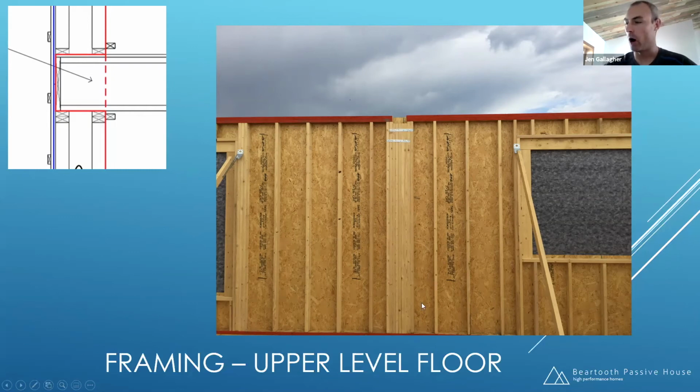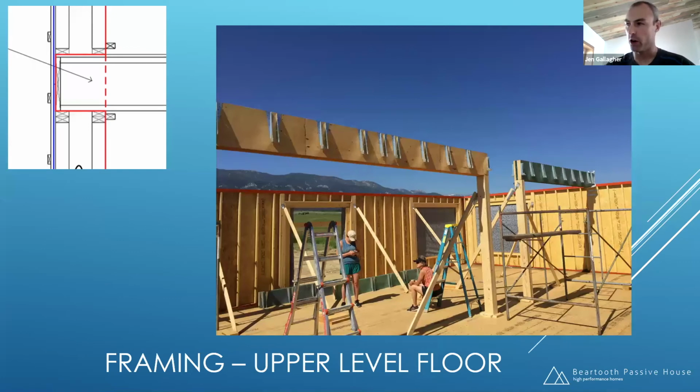Okay. Now I know that when I get to it, I've got to get my air barrier from inside, and I've got to get it out and around, back up. What I didn't really account for is that it's really tricky figuring out how you keep a beam sitting on here really, really airtight. It wasn't hard when you thought about it, but had I thought about it a little bit more in advance, it would have been less stressful whenever I did it.